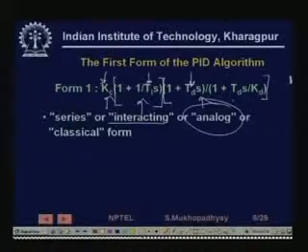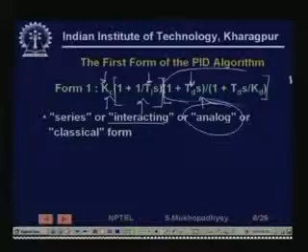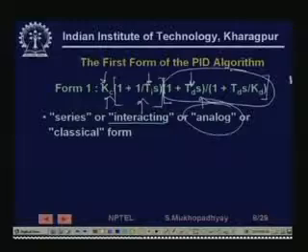This is called analog because this controller has its origin in the old days pneumatic controls. Actually, it turns out that it was easier to generate the PID equation in this form using pneumatic elements, things like orifices and then bellows, flapper nozzles. So with such things it is easy to build it in this form and not in the parallel form, right.